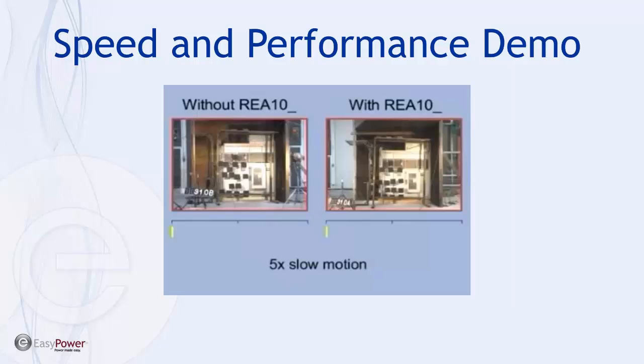On the right, we're going to use the REA arc flash system. We're going to trip the upstream breaker, and then we can see also that there's a significant difference in the explosion potential when you're using an REA arc flash device instead of traditional protection, overcurrent relaying, instantaneous differential. So we'll go ahead and take a look at this video.